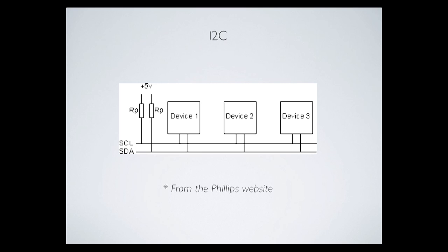And as part of the protocol, when it communicates on the wire, you have one master and a bunch of slaves. The master can request information or control any device that has an address on that line. We'll look at the protocol next, but basically what happens is you send out a start, and then you send out an address, so which device you want to talk to.